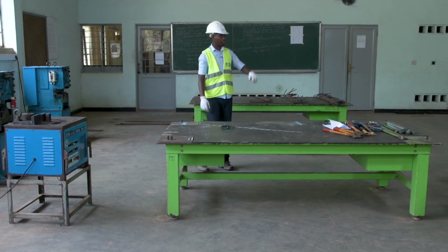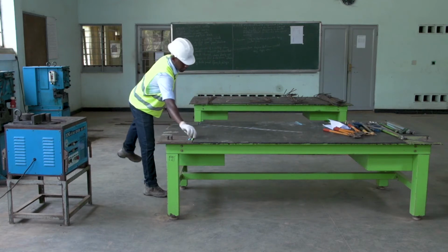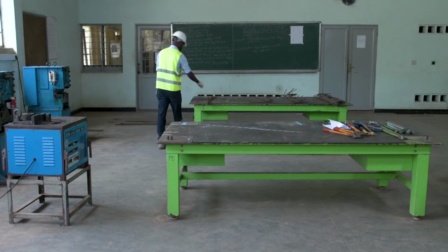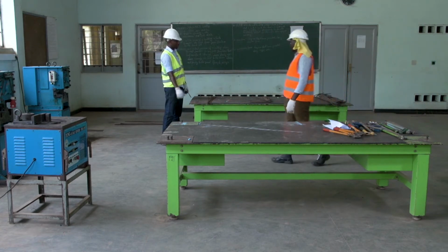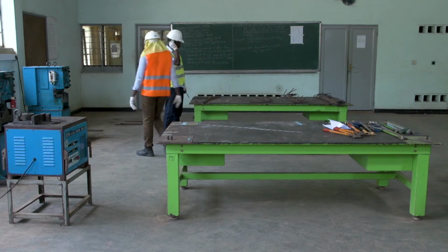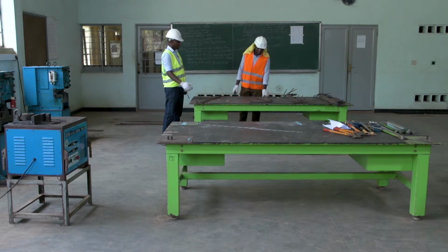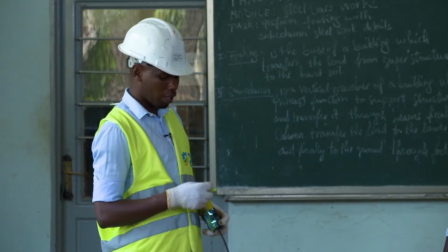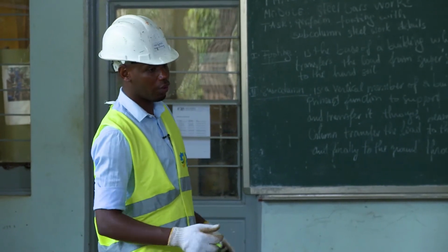And the next step, according to our work, we have 3 types of steel bars we need to bend, or I can say 4 types because you have a square footing. We have finished to bend a distribution bar and the main bar for the footing, and you have finished to bend the bars for subcolumns. Now we are going to bend the stirrup for our subcolumn.